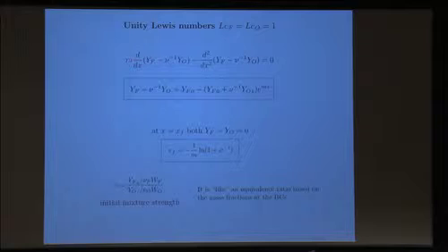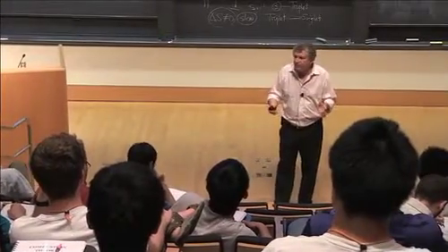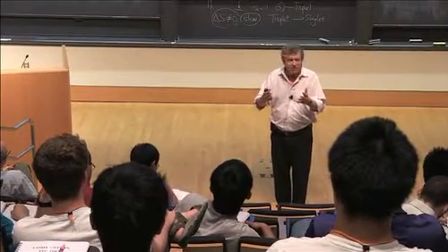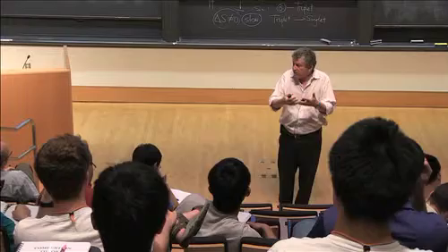Now, the nice thing in diffusion flame is that if you set both YF and YO equal to 0, that happens when x is xF, so immediately you have an equation for the location of the reaction sheet. So xF is given by 1 over m, the log of whatever the quantity here, which I call 1 over phi. And phi is very similar to what we call in premixed combustion the equivalence ratio, except that there is no exact meaning to equivalence ratio in a diffusion flame, because the ratio of the mass of fuel to oxidizer changes as they diffuse against each other.